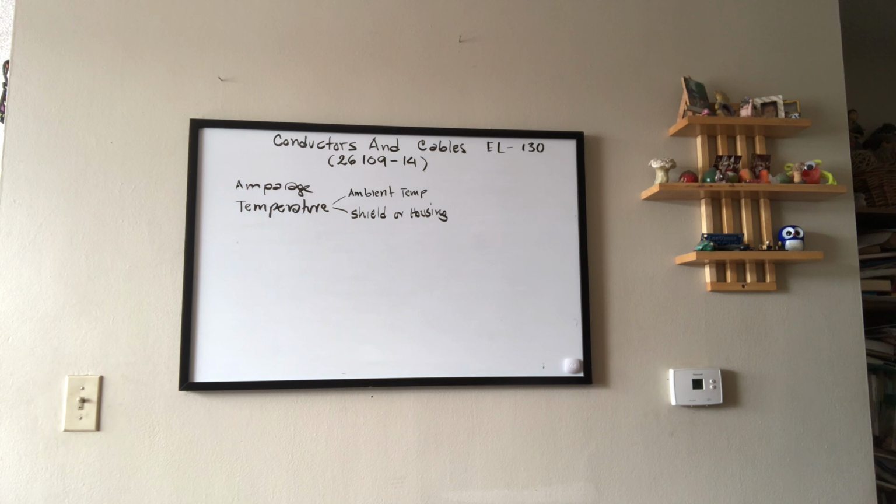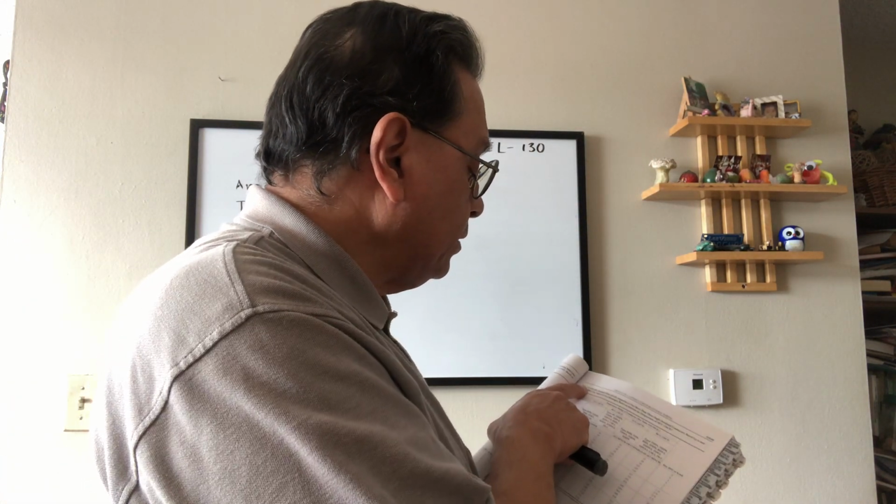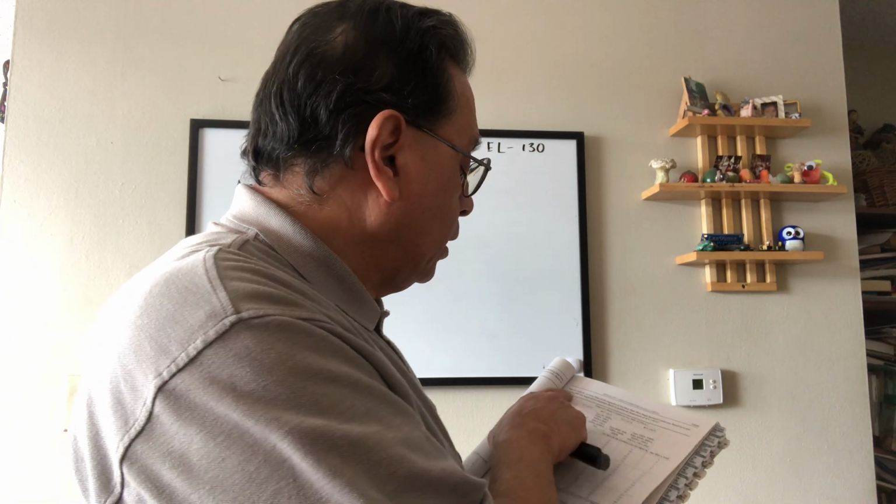One table on the NEC. So the table, let me see, 310.15(B)(20), ampacity for no more than 3 single insulated conductors rated up to 2000 volts, supported on a base or ambient temperature of 40 degrees. That is one table.